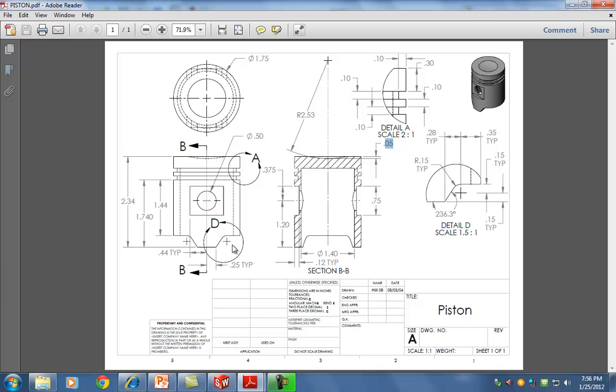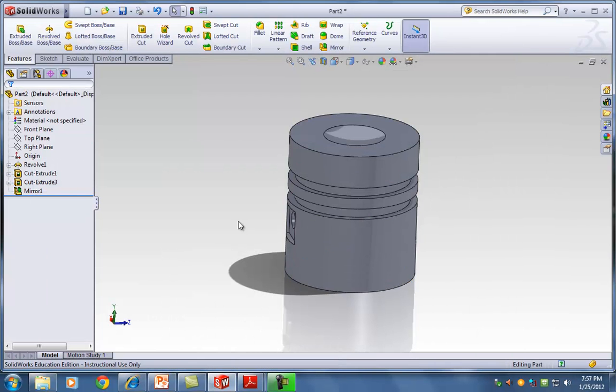Well, after we do all these parts, I'm going to give you these drawings, and tell me if there are any errors on this drawing. I'm telling you from now that this drawing does have an error in rounding. It's not major. This should be 0.275, but if you round it, it's 0.28. The way that you read the drawings is you always dimension from this side to this side. So by the time you apply all these dimensions and you get here, it is already fully defined, so you don't even need this number. Does that make sense?